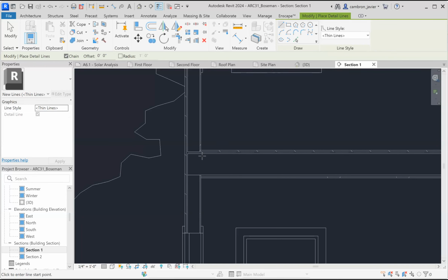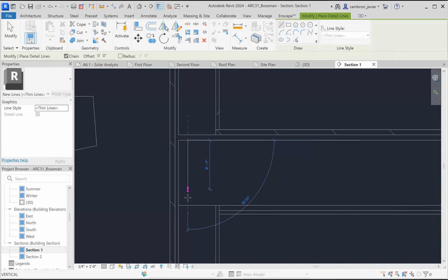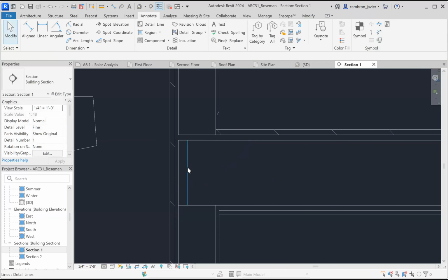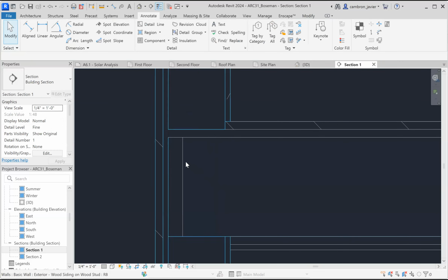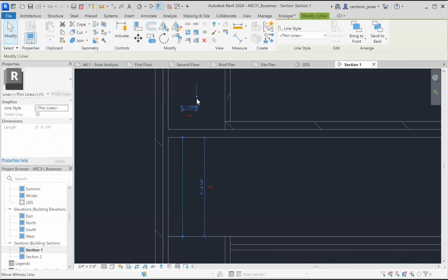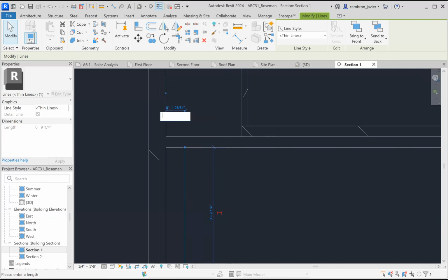So if I wanted to draw, let's say, the floor joist, right over here, I can draw this line just like that. I can select this line and then specify the temporary dimension. Let's bring this over. Oh, of course it doesn't want to come over. So let's bring this, there we go, right there. And let's make this 0, 1 and 1/2, which represents a 2 by.